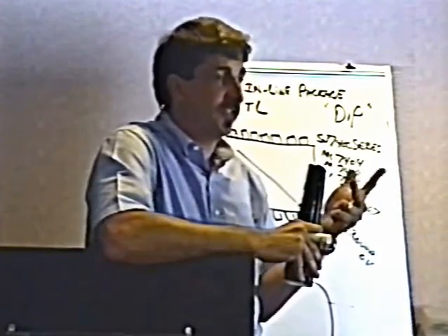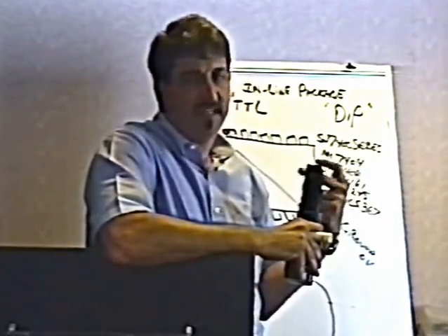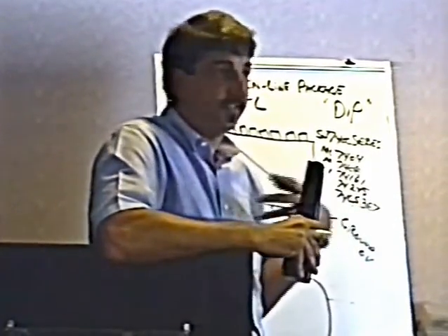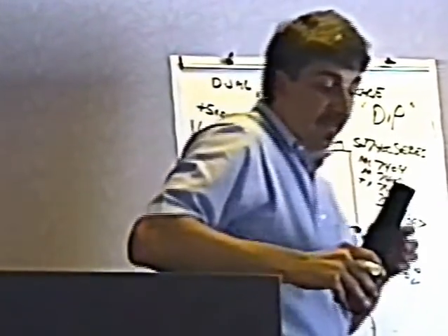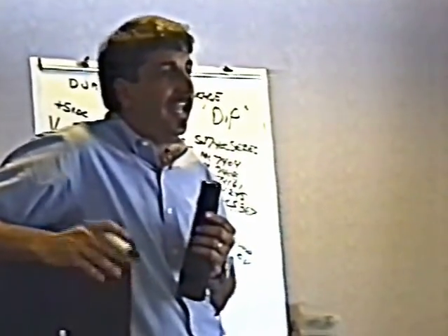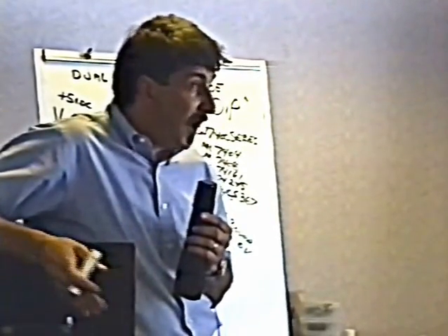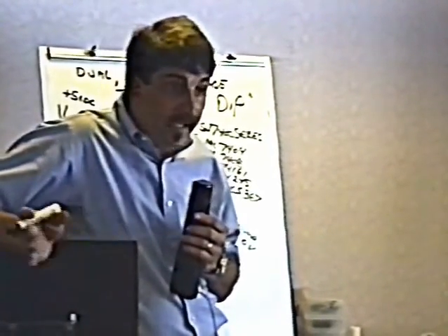resistor transistor logic. They called it RTL. Didn't work with beans. Then they came up with something called DTL, diode transistor logic. Didn't work with beans. Then they invented this stuff called TTL, and TTL works great. Almost every integrated circuit in every game we work on is what we call a TTL chip. It works really great. It's almost indestructible. It's easy to design with.